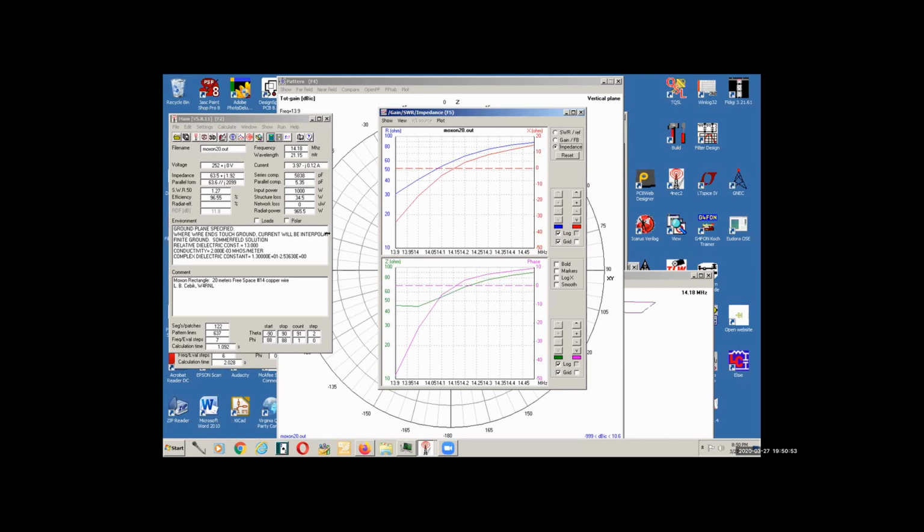But if I'm modeling a dipole, a Yagi up in the air, the Moxon, a log periodic array, it probably is not going to make any difference. And that's kind of what I was trying to show in the first example I gave, where I took my delta loop and got basically the same feed point impedance and the same pattern with both NEC-2 and NEC-4.